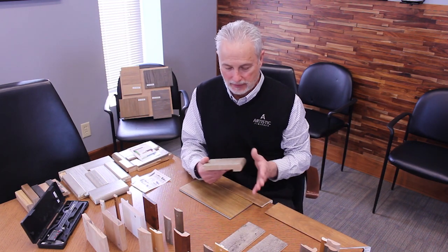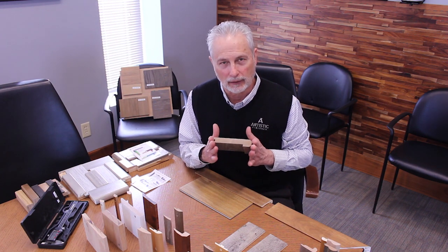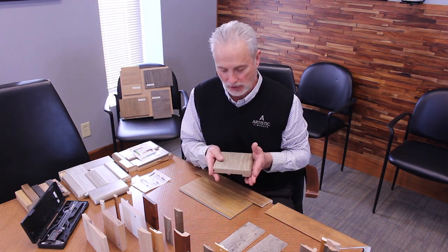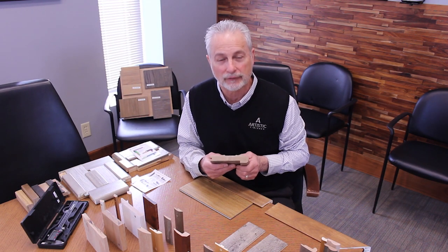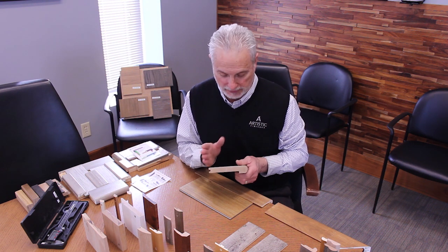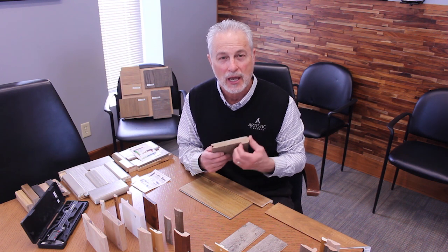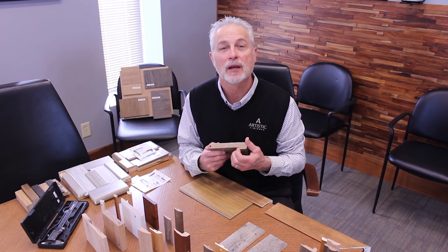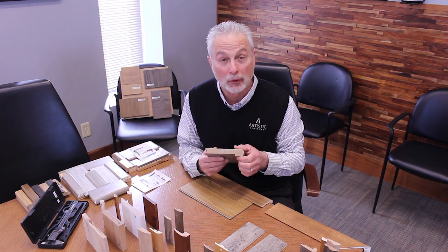Back in the day, when you had 3/4 solid floor, you were looking at a lot of landing tread. Now, these are running 5.5 inches wide, also in thinner thicknesses. We go down to a 1/2 inch, where it gets a little narrower, but still maintains the full radius bullnose on a 1.25 inch sized bullnose. A component of a stair nosing, the bullnosing.